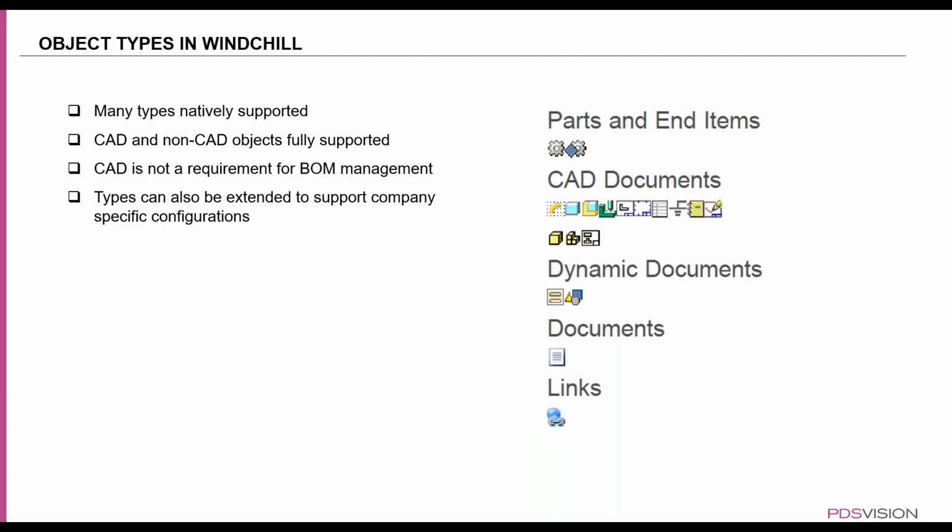Right, so in Windchill, there's a couple of business objects that they use to manage this information. And this basically maintains or captures a lot of types of information here. So CAD information, like the SolidWorks information, your CATIA, Creo Parametric information, Inventor information can be captured in the system here, and also non-CAD objects.